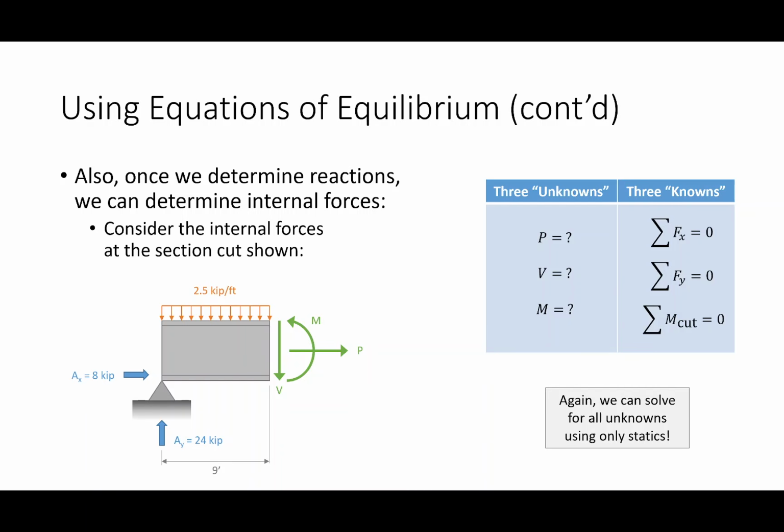Now, to be clear, that analysis, that idea extends not just to external equilibrium, but internal equilibrium as well. For example, one of the things that we're going to move past real quick in here is external equilibrium, and we're going to look at internal forces. For example, I am sitting here on this table. Not only does the table legs have to provide forces to keep the table in equilibrium, but the table itself has to develop internal forces to keep me upright. And it is those internal forces that we would design for.